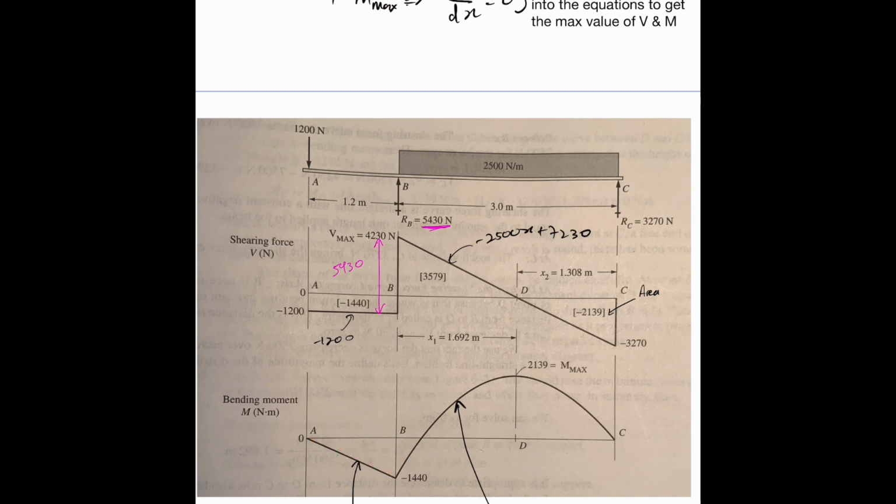As one would expect, if you apply a load here and you pivot here, this beam is going to bend up like this, and then eventually it will bend down due to that load. So this is how the deflection of this beam is going to look. So based on that bending moment diagram, we could approximate how the bending of the beam will look.